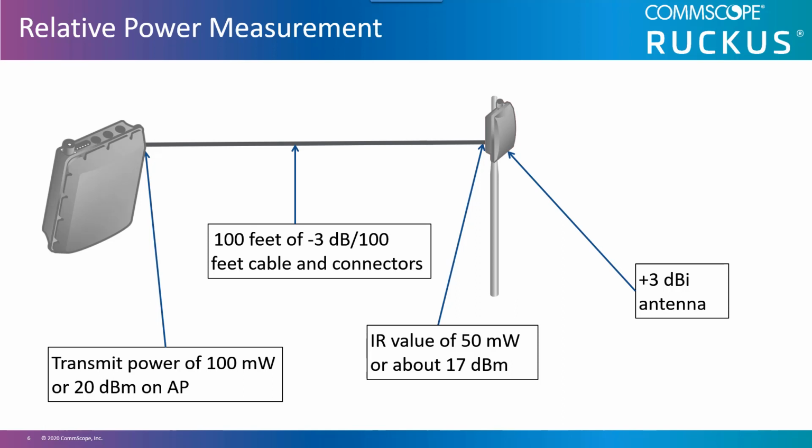The measurement taken here is the equivalent isotropically radiated power, or EIRP. It is the product of transmitted power, any connectors, cable loss introduced, any amplification, any attenuation created there, any imperfections, any voltage standing wave ratio problems where you have impedance mismatch between connectors and cables.